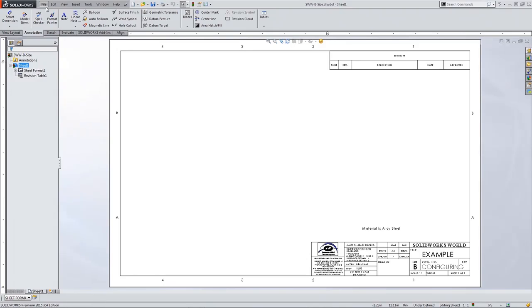At the bottom, when you do properties, you can say which view you're referencing to fill in the properties in your title block. So on your second sheet, couldn't you just specify a different view that is in your second sheet that would have those different part numbers? You're saying there's a right-click option on a sheet to say which view to reference? I'm asking, because I know on the first sheet you can pick which view, so it defaults to the first view that you add, right? Okay, so you can actually select a different view. Oh, like have a different part number. And okay, it'll fill in the title block with that. Well, that sounds like an excellent thing to check out. I'm not familiar with that, so thanks for sharing that.